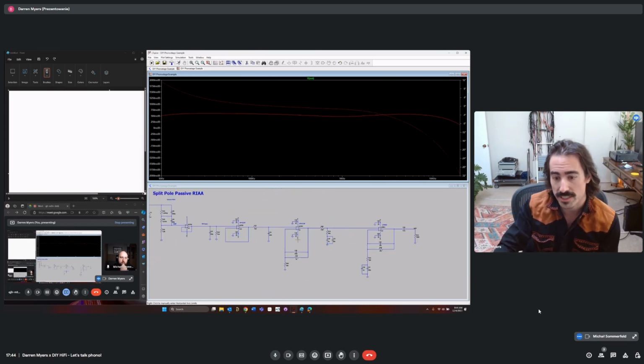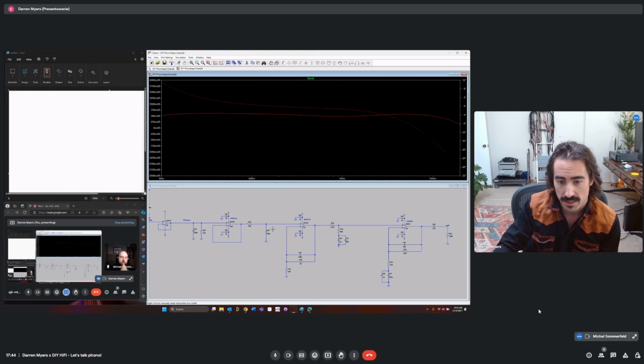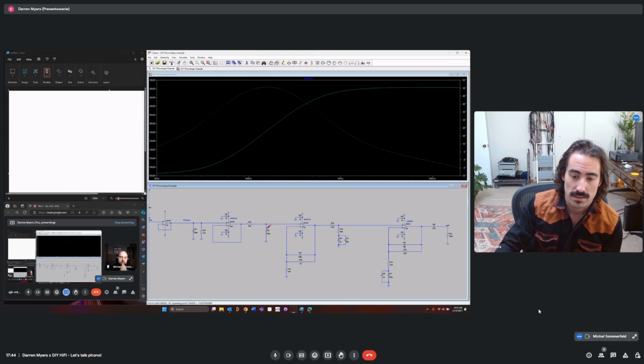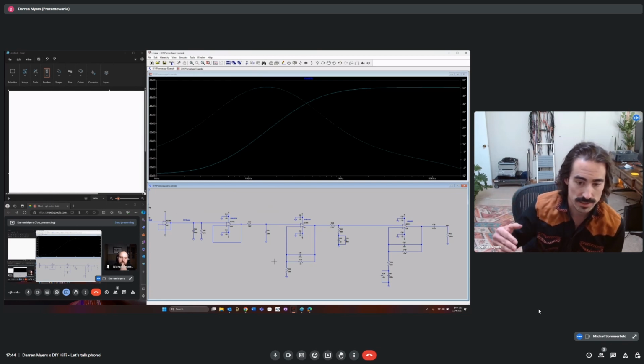But why have we done this? Why have we applied the time constant so early? The advantage here is just that we knock the top down earlier. So we bring in some of the advantages of that hybrid design, which was number one, with the passive design, which was the second design we talked about. And we kind of get the best of both worlds, other than having to add in another stage and having R19 be on the line of dominating noise in this design.